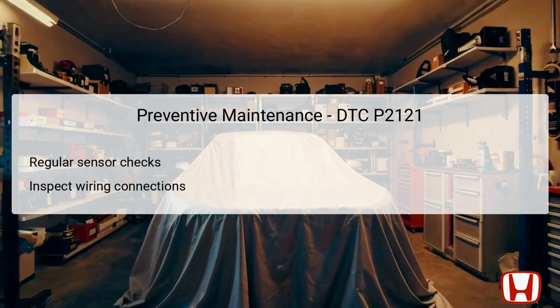To avoid future issues with the APP sensor and to maintain vehicle performance, regular preventive maintenance should be implemented. Schedule periodic checks on the APP sensor A and its associated wiring. Often, simply ensuring all connections are clean, tight, and free of corrosion can prevent faults from occurring. Inspect the electrical harness for any signs of wear or damage, as this can lead to intermittent failures that may trigger DTC P2121. Addressing small issues proactively can save time and money down the road, keeping the vehicle running smoothly and efficiently.